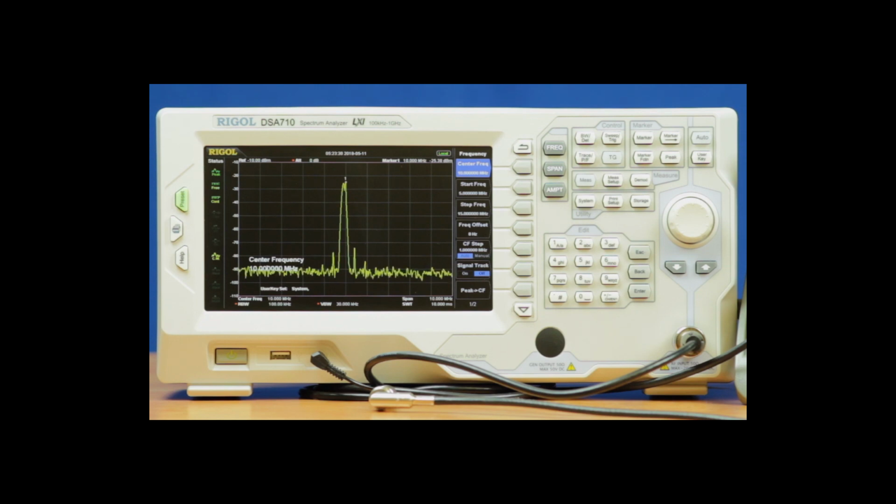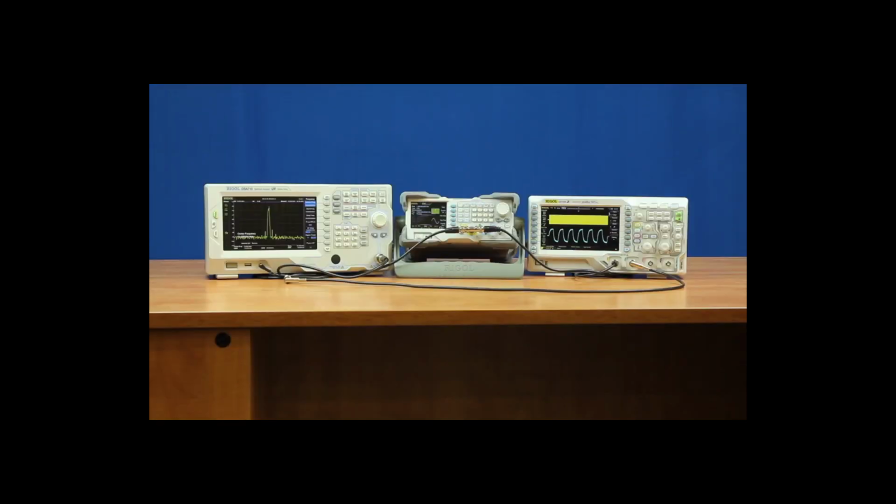So at a 1 kilohertz frequency, that input is changing, that bit is changing, and the spectrum analyzer cleanly can pick out the highs and the lows, even though those frequencies are close together. And that's one of the advantages of the frequency domain, is the ability to easily separate nearby frequencies together using the RBW settings and the demodulation settings on the spectrum analyzer.